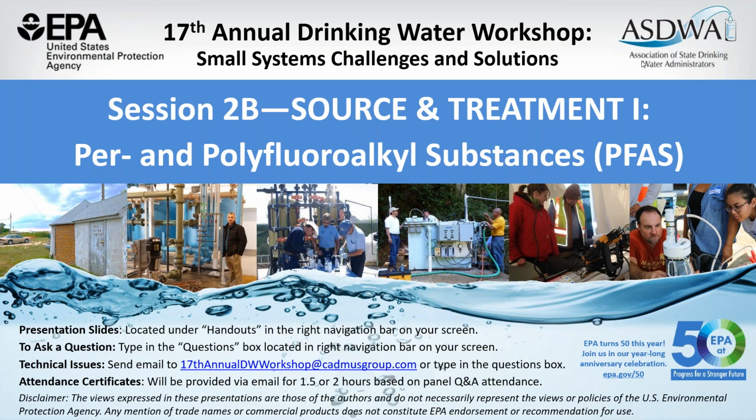And to throw in regulations in general, what's going to happen for PFOA, the MCL that'll be set nationally, and what are states going to be doing and regulating for other PFAS? Scott was highlighting PFBA and some of these shorter chains that rip through carbon a lot quicker. So it makes designing now difficult. You'd hate to put something in now that works, only to find out later down the road the game's changed, based on what you're seeing in your influent or other PFAS of concern. Those are just other considerations for states and others to be aware of.